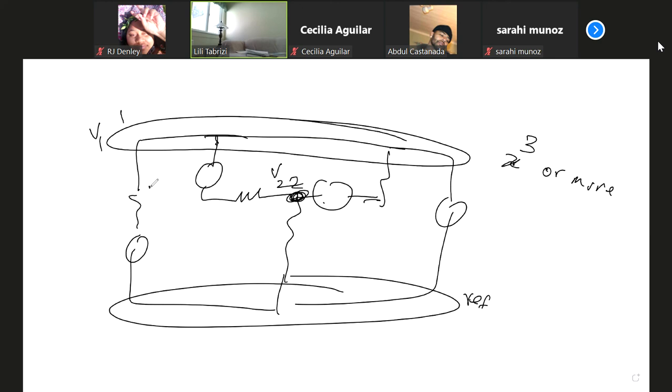And then we assign a current in any direction to any resistor in the circuit. So this was the preparation process for node 1. For essential nodes, you have to check your circuit to see which nodes, other than the reference, have three or more lines connected. If that is a node with three or more elements, then it's an essential node, and it's the node that you're using for your nodal analysis.